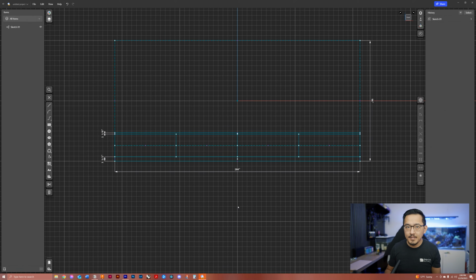So now let's start drawing the actual cabinet boxes. Remember when I showed you earlier about creating a box and using the shell tool to make the box? It doesn't work parametrically when I make those copies, as we saw earlier. I have to do a little bit more work, a little bit more modification. So what we're going to do is establish all of our guidelines to make the panels. And you could do this in 2 ways. You could actually model out each panel, or you can draw the entire cabinet box and then use the split tool later on to make the individual panels for measurements.